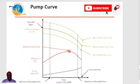The effects of the impeller diameter on pump performance are what you can see on this. If you look at these different pump curves, you have the maximum impeller diameter curve. You can see the rated impeller diameter curve. If your pump has the rated impeller diameter, the behavior of the pump will be based on this rated impeller diameter curve.